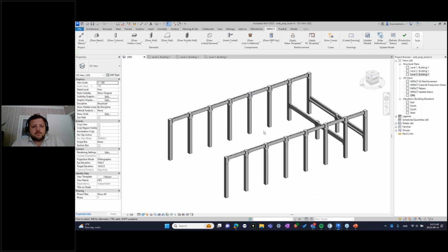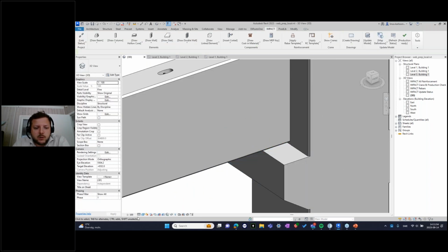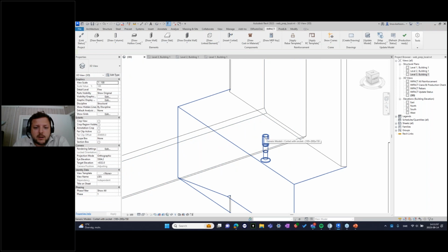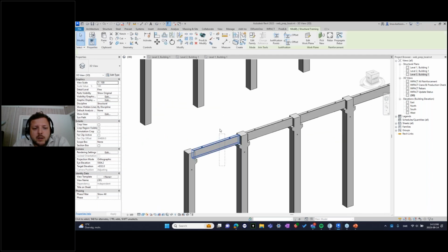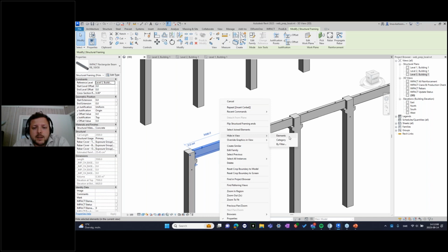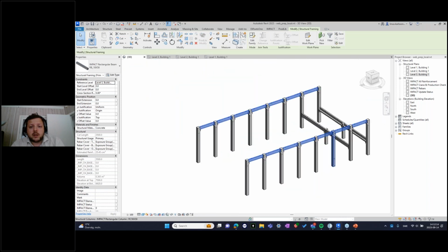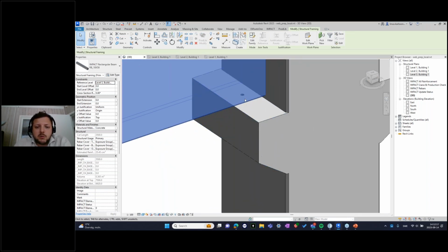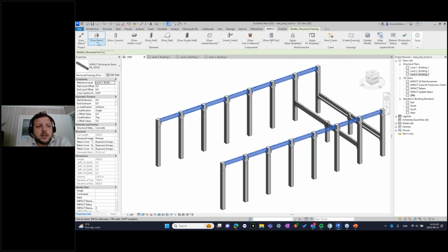So that's great. One more thing that we can do is you can see here now when we inserted the corbel, we get the cast material to connect the beam and the corbel. So we need to prepare that for the beams as well. So I will select, oh, sorry, that's wrong. I will select all these rectangular beams because I did some measurements before. So I don't need to measure. I know how the connection is going to be. So what I do is go here and I go to edit beam.